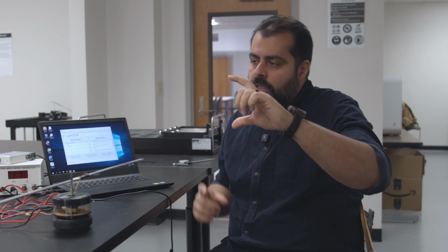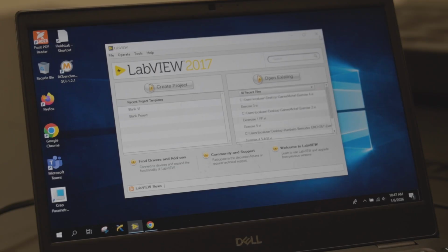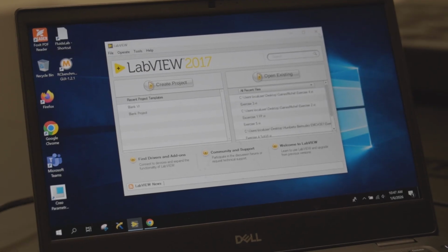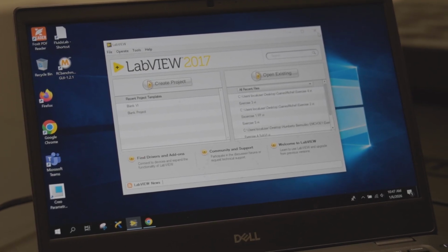So you take the first amplitude and the last amplitude, you know how many periods there have been, so you know the number n, and you know the amplitudes. Using those, we are going to give you an equation to calculate the damping ratio of this specific beam. So the first step of this part of the lab is to set up the LabVIEW program.